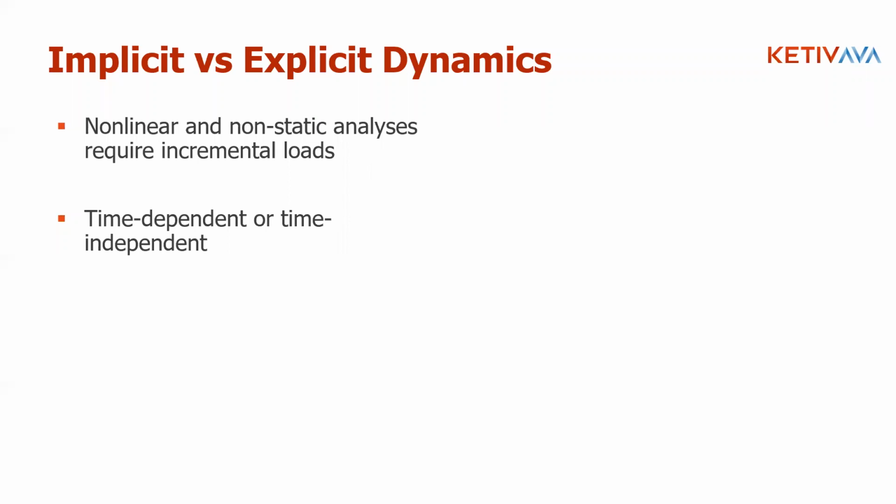Once again, with implicit and explicit dynamics, these loads can either be time dependent or time independent. In any case, though, you're never looking at a nonlinear analysis with a load that is time independent, because again, that would be an approximation. Even if you're saying it's time dependent, there is some degree of ramp up with the load. The load will be increased from 0 to full load at some point, and so it's important to capture that as well.